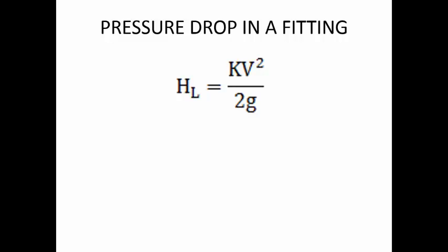If you don't know this, what happens is this. Consider that your pump has a capacity to generate a pressure up to a maximum of 100 bar, and accordingly you have a motor, say a 3 HP motor or a 5 HP motor. Your actuator also requires, say, 100 bar of pressure.